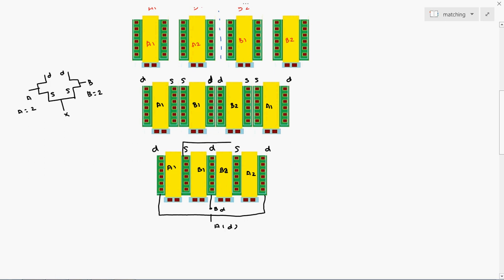So source and source terminals are shorted, and we can give this as the common X output of A and B. I mentioned the X output here, so this is the X net. This is how the transistors are merged with the interdigitization based pattern, and how we give the source and drain connections, implementing the new pattern we have chosen.